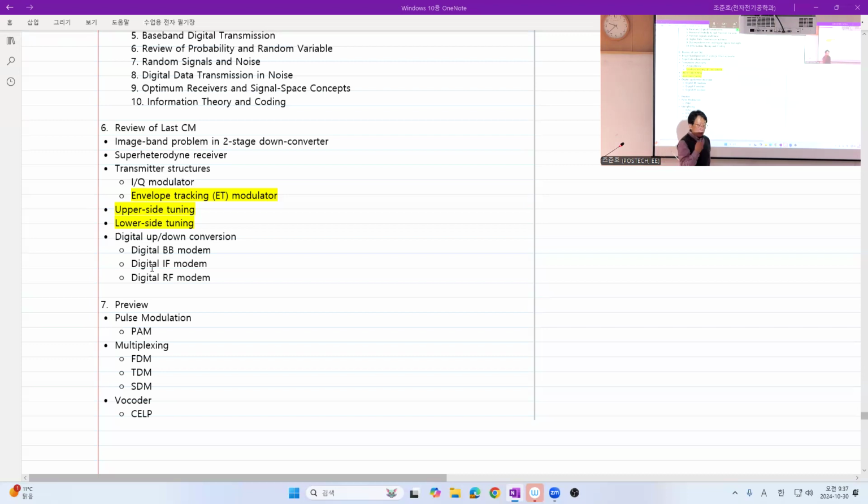So if devising that bandpass filter and implementing it is of lower cost than having a single direct upconversion filter, you adopt that structure. So that is one of the most important lessons we can obtain from the history or development of this heterodyne idea.